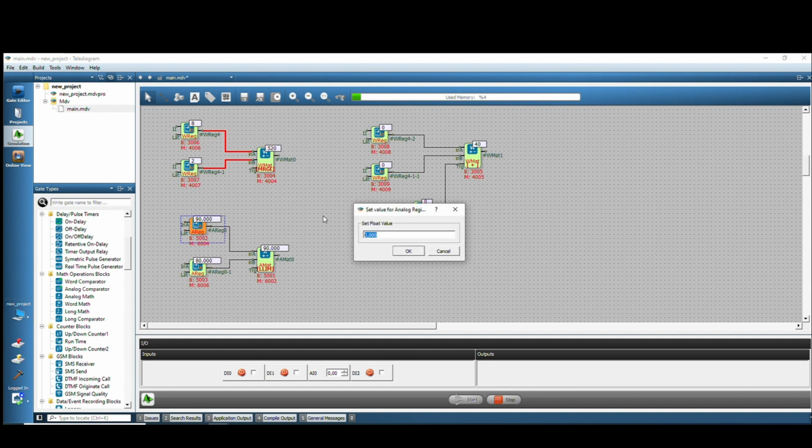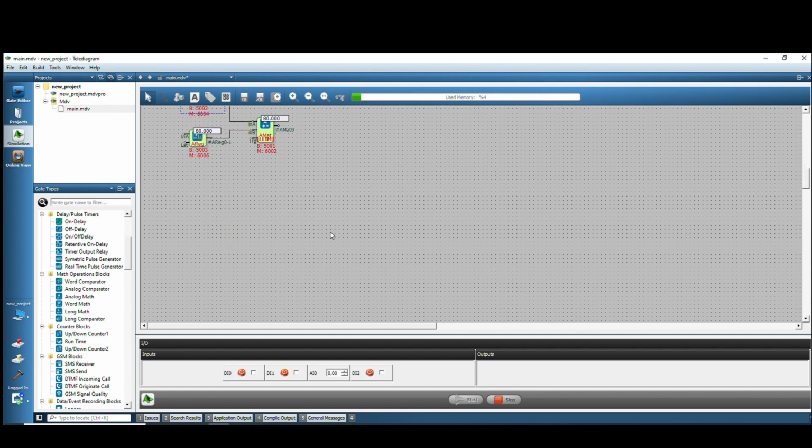But any value below 80 will always transfer the value 80 to the output as it accepts the lower limit as 80. In high limit, similarly, it will transfer the value entering the in B input to the output at the exceedance of the high limit. No output process will be made above that limit in any way. Thus, we have completed the operation blocks.